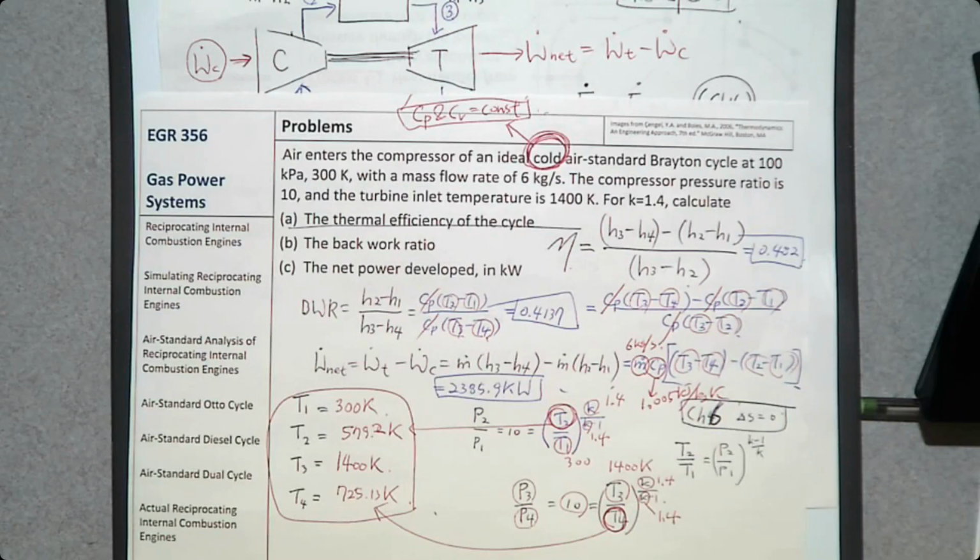That is light water nuclear reactor. And if you want to increase the turbine inlet temperature slightly, then people use heavy water nuclear reactor because that has slightly higher maximum allowable temperature. But if you use a gas turbine, you can increase that significantly because you don't have to rely on water. Okay?